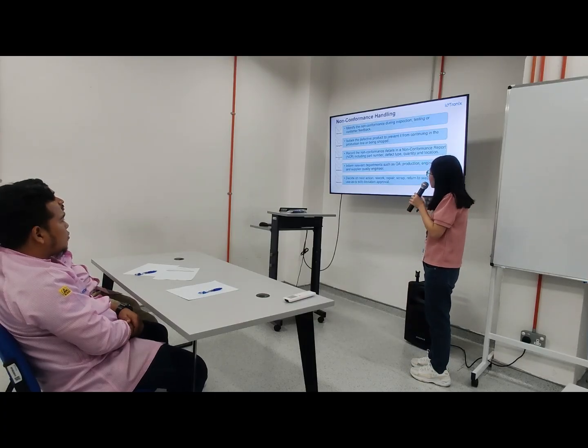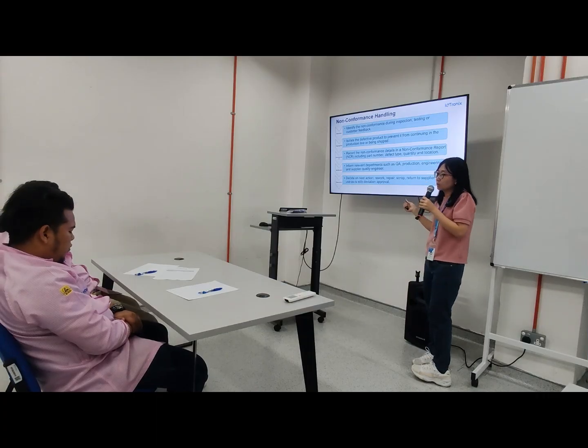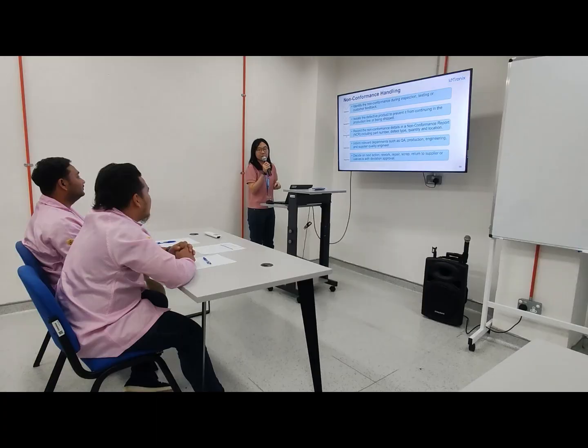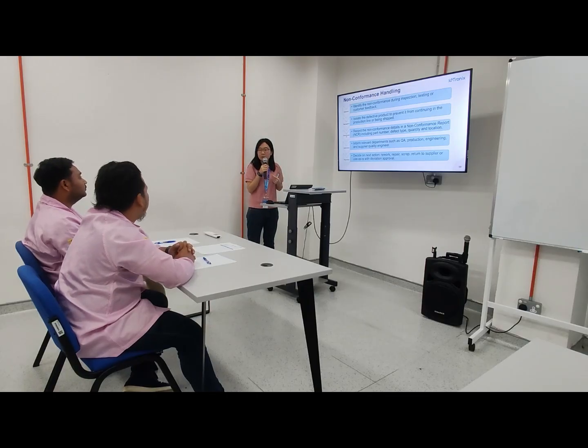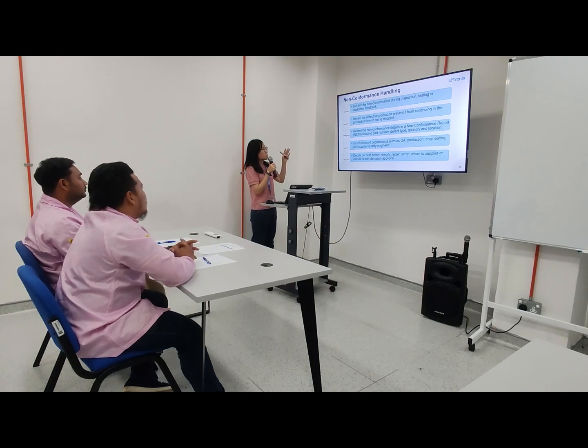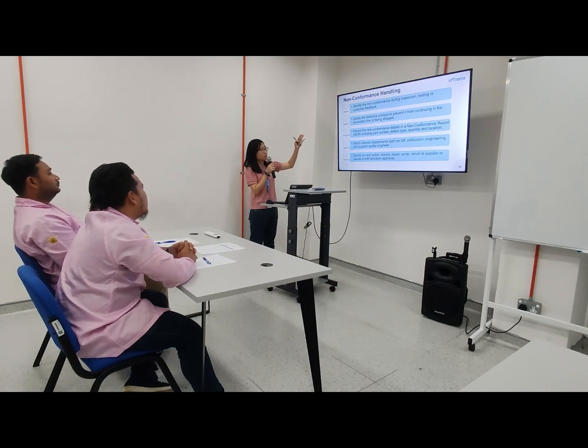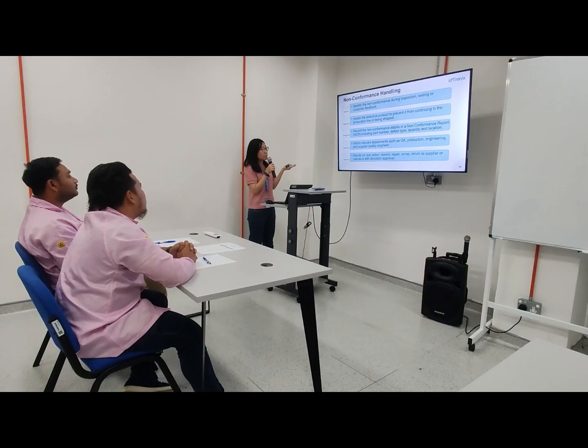Okay, I think later we continue now. Okay, let's continue for non-conformance handling. Okay, actually non-conformance, the meaning also same with defect lah. Means those that do not meet the standard requirement, customer requirement. Okay, first is the detection. First we detect, identify what is the non-conformance during inspection, testing, or customer feedback. After identify, then we will segregate.